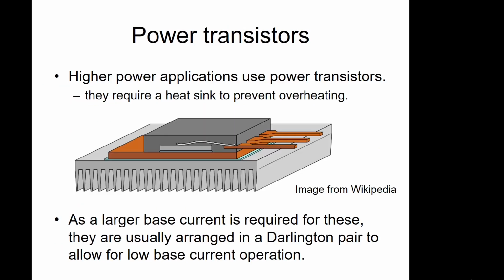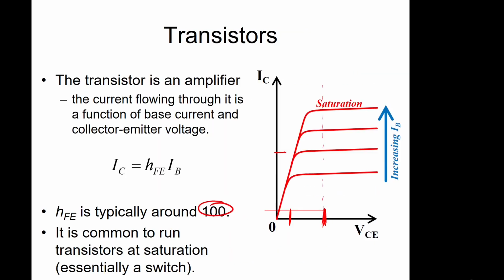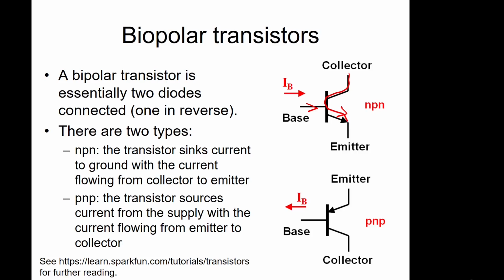Now a typical use for transistors is to power motors. So you put your current in, your transistor, you have your motor connected here, your voltage source. There's no current flow, you're operating it as a switch. So you put some current in there. Current is then allowed to flow through the motor and down to earth, and the motor turns.